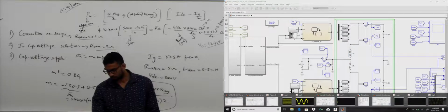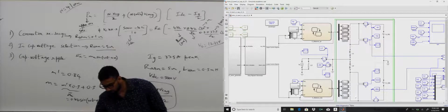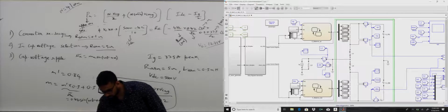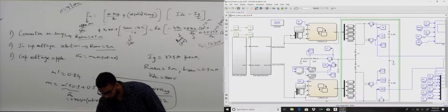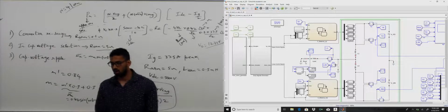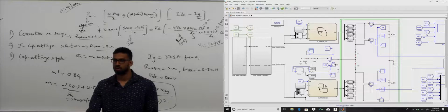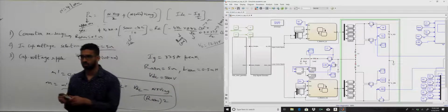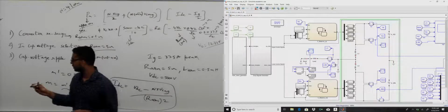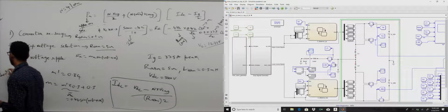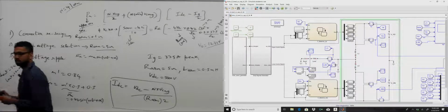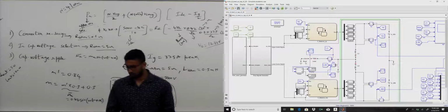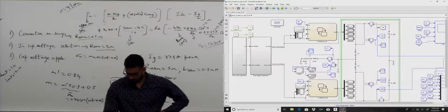And then for the first question again, you need to change these values, right? R out and L out. In the simulation that's given to you, you will also have an AC source. Delete the AC source and set R out and L out to the value given in the question. That will be R out 50 ohms and L out 10 millihenry. Set those to that value, and then